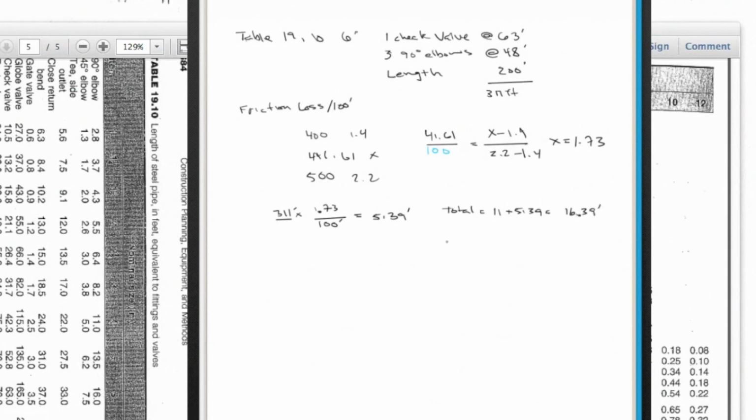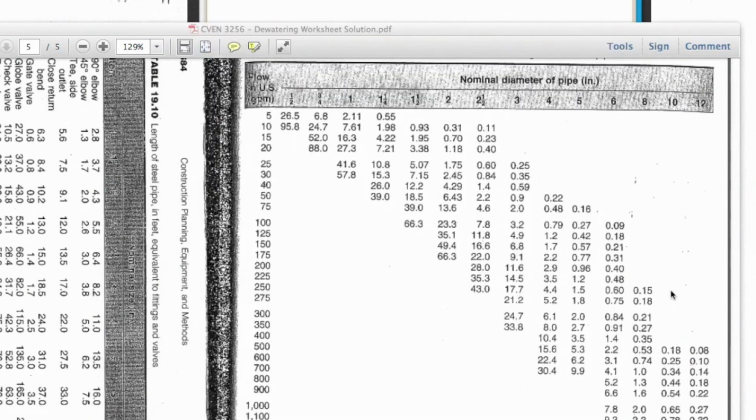Okay, if we look at now the table using this 441, going back to table 19.8, we looked at our initial draw pumps, we checked those out. Now if we use 20 feet of head, just rounding up to be even more conservative, and 10 feet above the water based on what we had, we can look at the table.